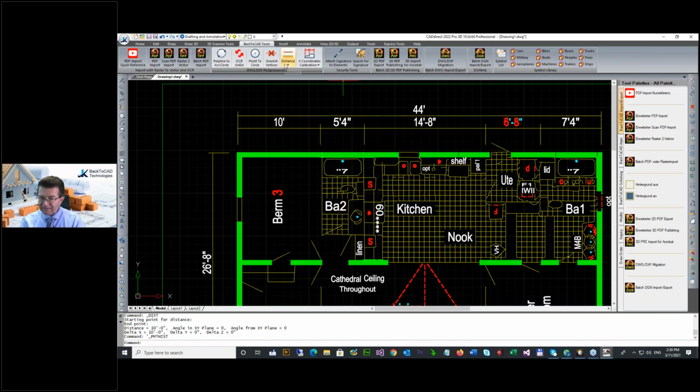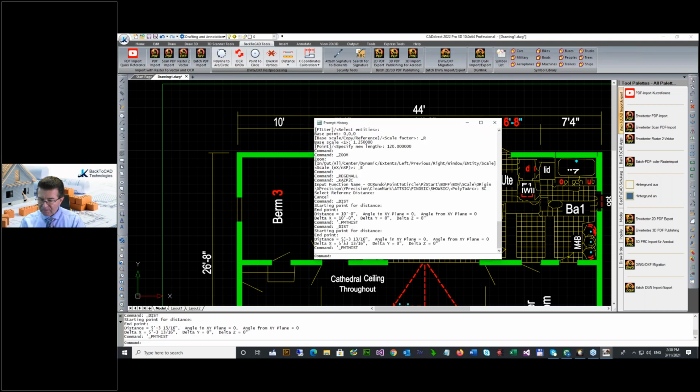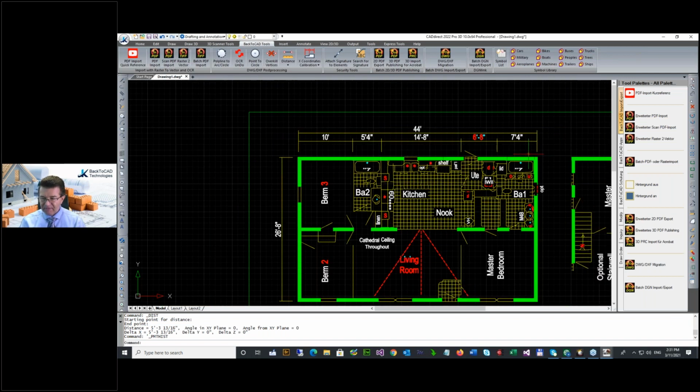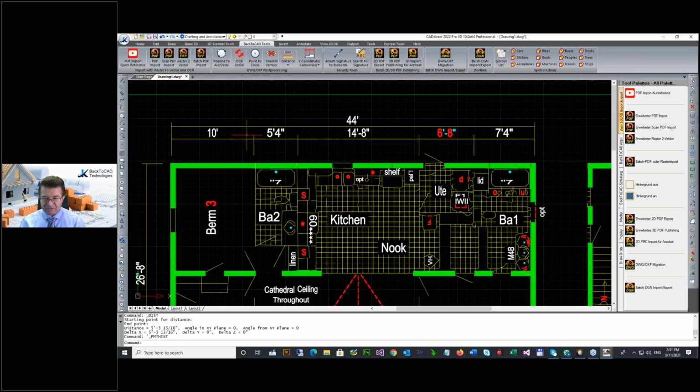But if you measure this distance, okay, you will never get 5.4, you will get less. Why? Because the drawing itself is inaccurate. You make only the inaccurate drawing bigger, but you didn't calibrate the coordinates. And now I will show you a very, very important function you can activate here under this viewer from Print to CAD. That's the calibration of coordinates.